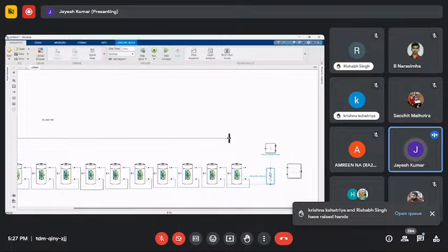I directly get the positive supply from here. But while measuring the current, we always connect the ammeter in series connection. So I have to connect this in series, and voltage should always be measured in parallel. So I have to connect the voltmeter in parallel across the load. So I have to give the negative supply.